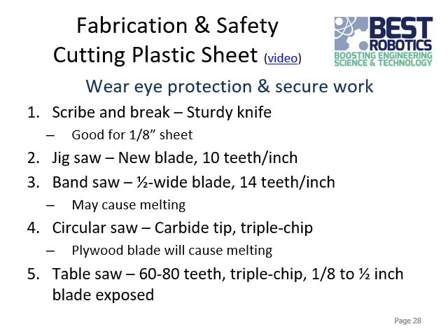So yeah, a couple different options for cutting plastic. One option that is pretty basic but can work well is just basically cutting it with a knife and then breaking it. This is good for really thin sheets. You can just use a straight edge, cut it with a utility knife or something sturdy, and usually you'll make a score along it the first time. And if you have a nice deep score, you can put a solid edge, like a straight edge or something, along that score line and break it off all at once. So that can work well.